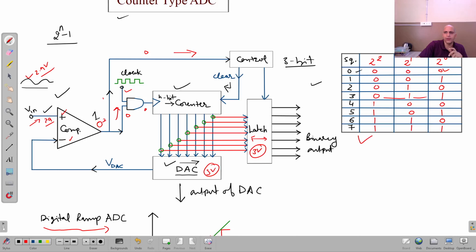I have shown you the table for this. But here one thing is very important. Here we have taken 8 levels, and the maximum value is 111, which is, sorry, 7 volt, if we are taking the reference as 1 equal to 7 volt. Then when we are doing the conversion, the peak to peak voltage should be 7 volt, because it can't proceed further than 7 volt. So the maximum value available in the input analog voltage should be either 7 or less than 7. Depending upon the bit requirement and the given voltage, we can make these adjustments.